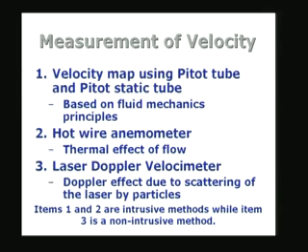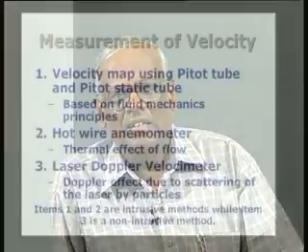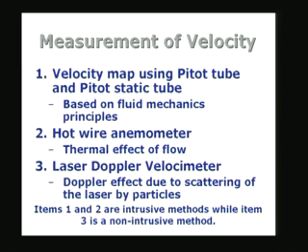The Doppler effect takes place when the laser light is scattered from particles which may be present naturally in the flow. When the flow contains some particles, if we assume that the particles are moving along with the flow at the same velocity, the laser beam is going to strike the particles, and therefore, they are going to scatter it, and because of the velocity of the particles, the light which is scattered is going to have a different frequency.